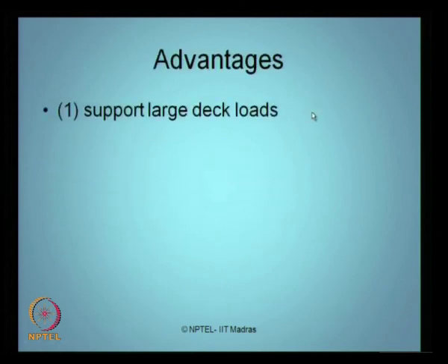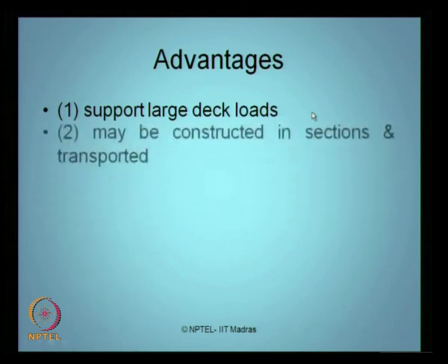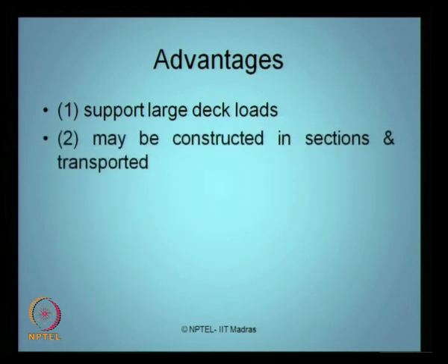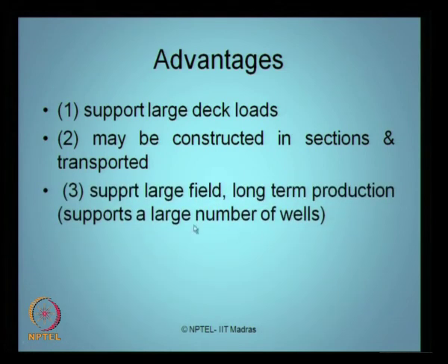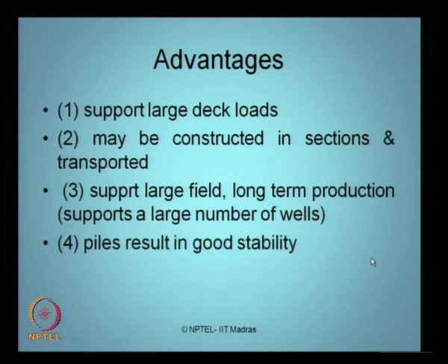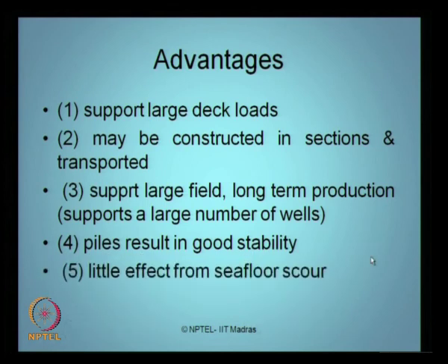There are a couple of advantages of jacket platforms. It supports large deck loads, and may be constructed in sections and transported, so installation becomes easy and simple. It supports large fields and long-term production; it can support a large number of wells. Piles result in good stability of the platform. It has very little effect from sea floor scouring, whereas gravity-based platforms are sensitive to sea floor scouring. There are a couple of disadvantages for these kinds of platforms: the cost increases exponentially with depth.